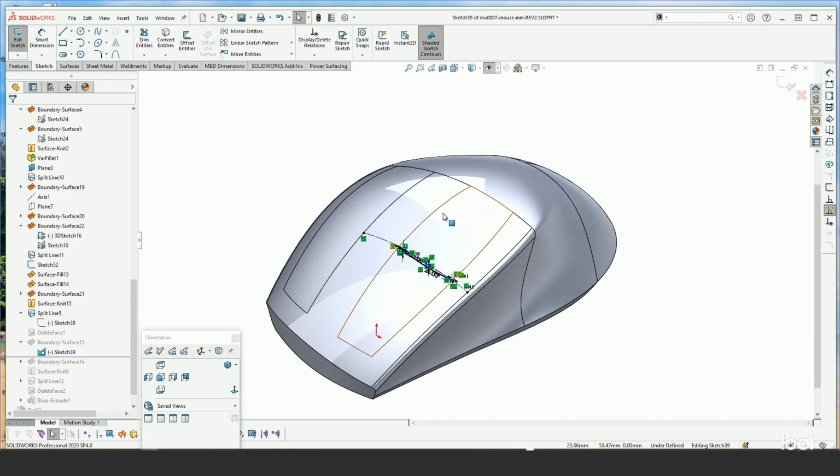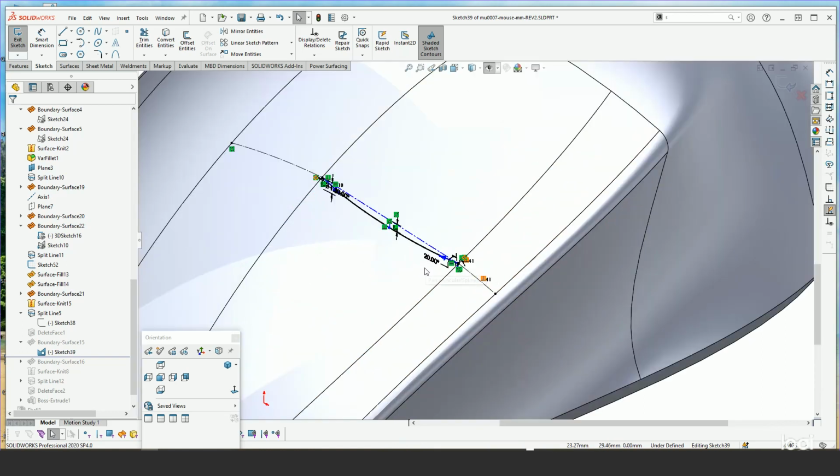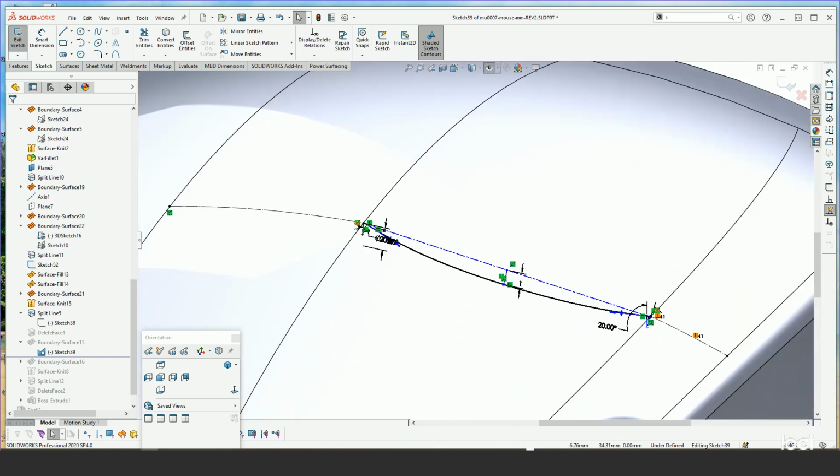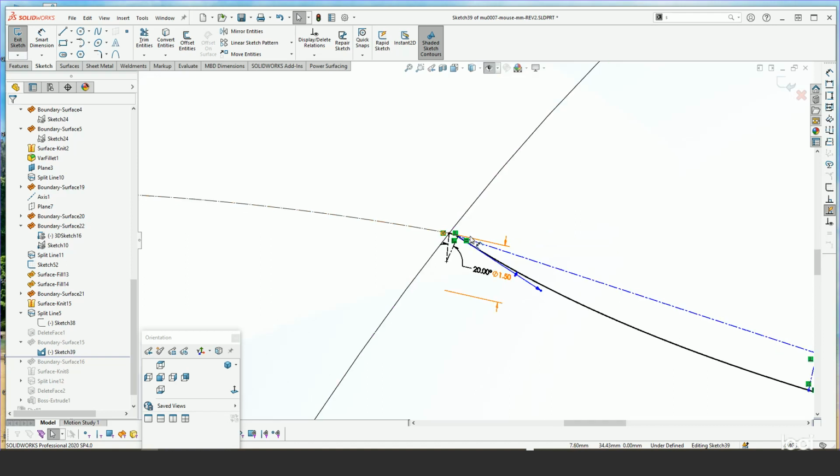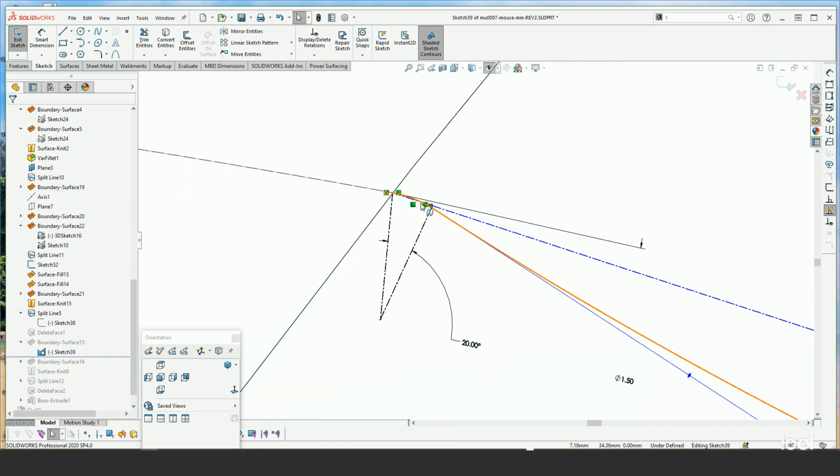And then our second direction will be simply these two edges. But with this sketch, we basically have used an intersection curve to derive tangency to the existing surface here, and then created an arc, with actually 3 arcs with a fit spline over it.